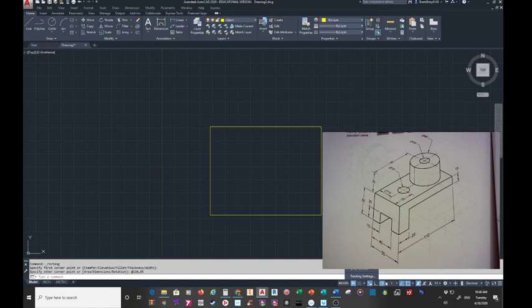You know, your old school people, they use ortho, but here I'm old school, and I've adapted and overcome because I think this is a really good tool because I can set this to lock. It'll keep moving, but it's like a little detent. It'll lock every however many degrees, 15, 18, 22 and a half, 30s. 15 works really well, so I have mine set on 15. So that's polar. Make sure it's on.